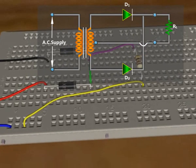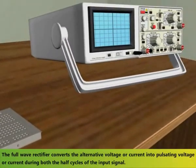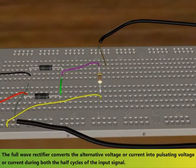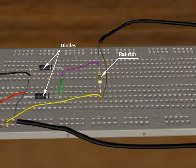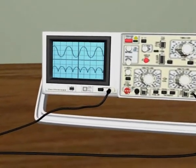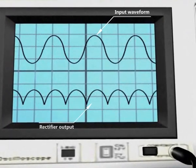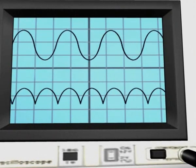The full wave rectifier is connected as shown in this diagram. The full wave rectifier converts the alternating voltage or current into pulsating voltage or current during both the half cycles of the input signal. There are diodes and resistors. The input signal and the rectifier output signal are shown in the CRO display.